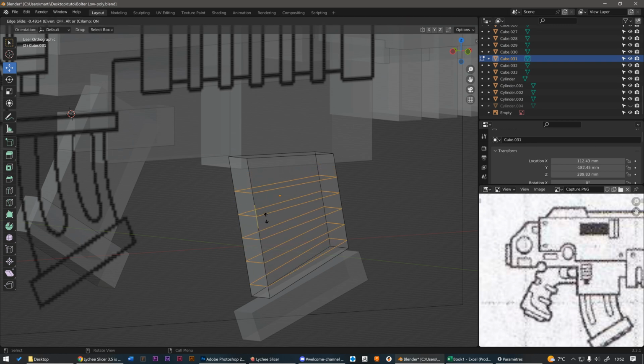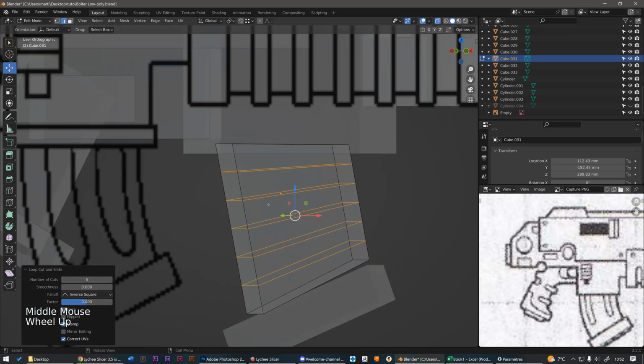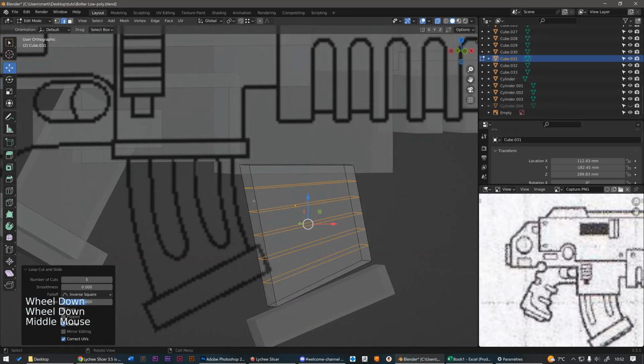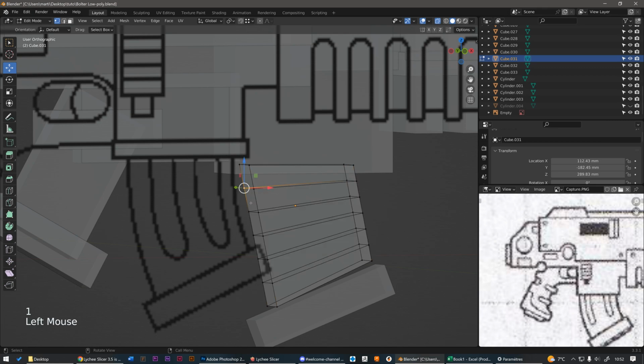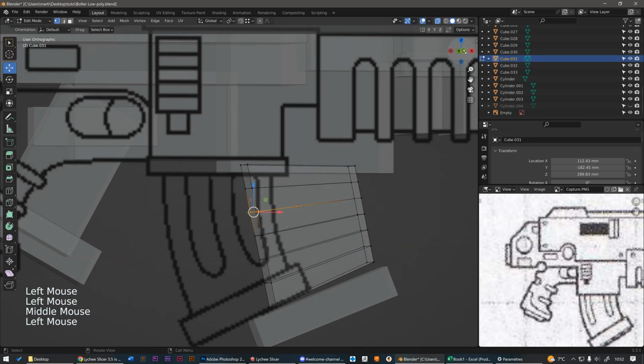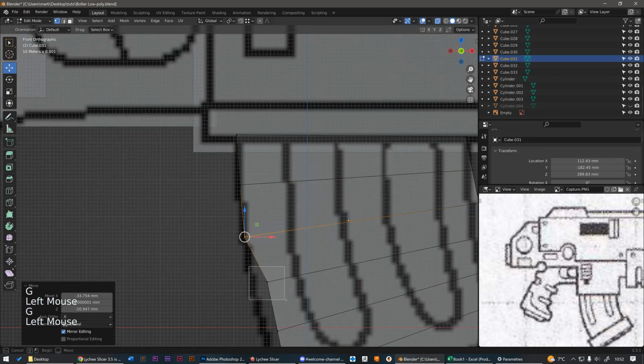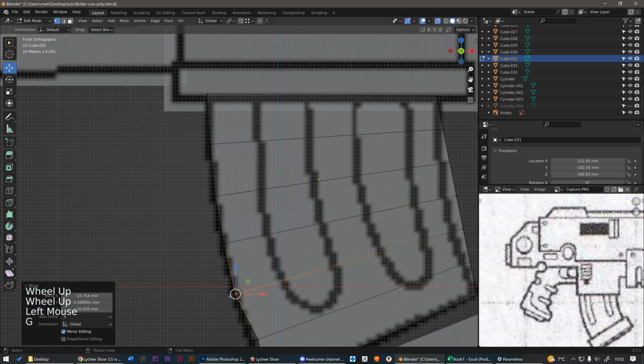So we just did the loop cut part. So now Blender lets us slide the loop we just created. Well, we don't really need to slide anything. So with a right click we can skip this step. It will distribute the loops in a balanced way. And there you go. Now we have our new topology, and therefore, if I switch to vertices mode with the 1 key, I will be able to move them. So I align the view again on the Y-axis. Then I can select vertices and position them to create a curve, following the drawing.